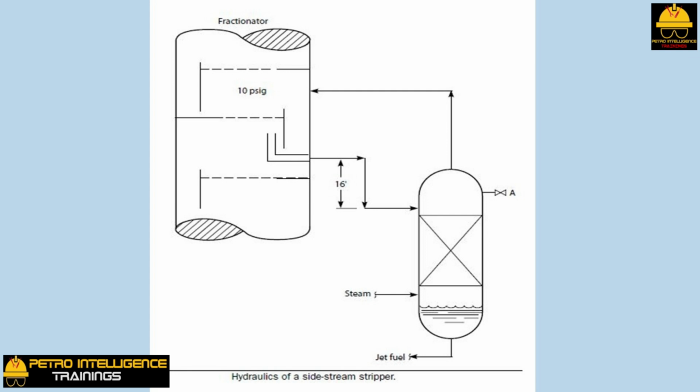The jet fuel product was steam stripped to remove a lighter naphtha contaminant. But much naphtha was left in the jet fuel. Apparently, the packing in the stripper tower was not working properly. However, a discussion with the unit operator indicated that they were using very little stripping steam. Introduction of a normal amount of steam resulted in a loss of liquid level in the bottom of the stripper.